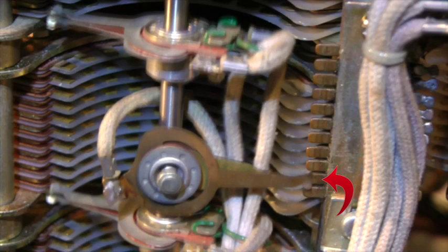If the commutator segment on which the commutator wiper rests is not grounded, then this level does not contain the bank terminals of the line requesting service, and more vertical stepping will be necessary. In our example, the line circuit terminal is on the 10th level of the bank assembly, and so there is no ground present on commutator segments 1 through 9. This vertical stepping cycle will be repeated for levels 2 through 9. Let's look at the level 2 stepping cycle.